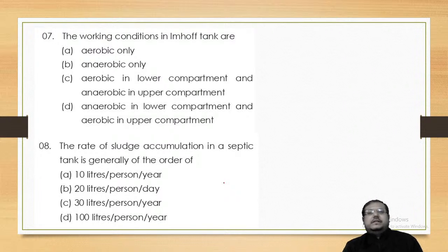The working conditions of an Imhoff tank: the upper compartment is for the settlement of solids and the lower compartment is for the digestion of settled solids. So obviously, in the Imhoff tank the lower compartment will always be anaerobic in nature. The upper compartment doesn't matter whether it is aerobic or anaerobic. So option D will be the correct answer.